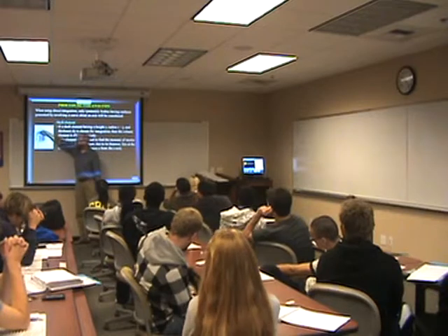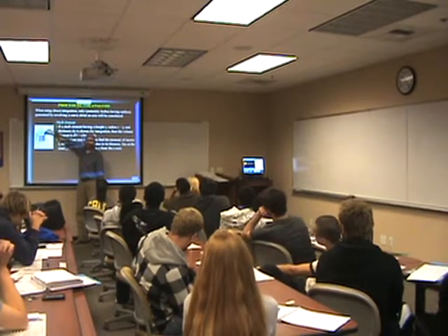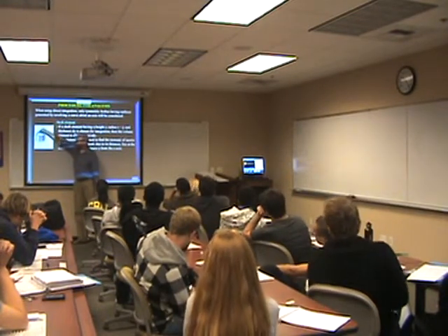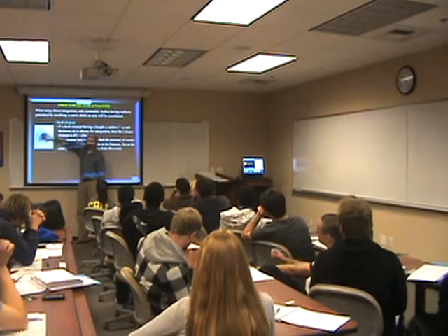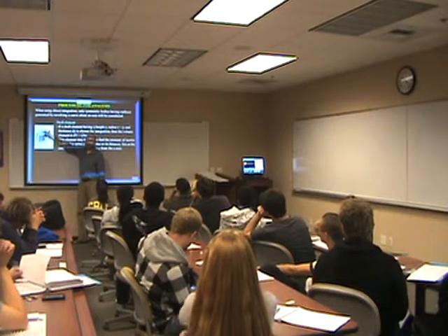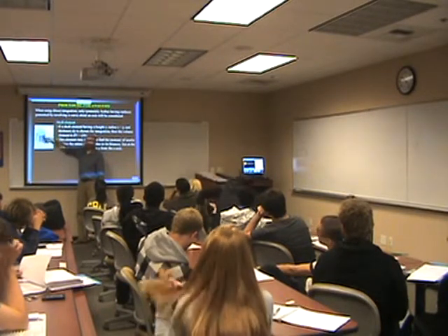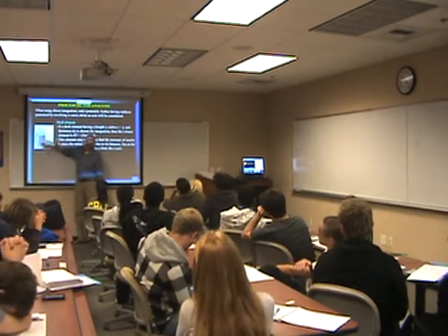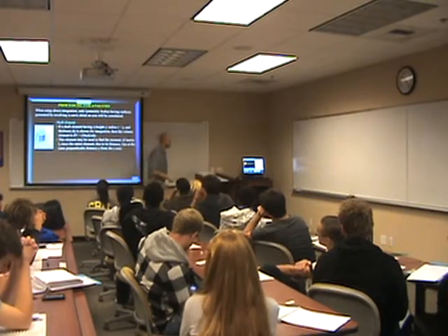It's the mass of the shell, and since this is a little dx, all the mass is located at the same distance away. So I for this is mass times radius squared. If we had the density, we would have to calculate the volume. But basically for a shell, the I is the mass times the radius squared.